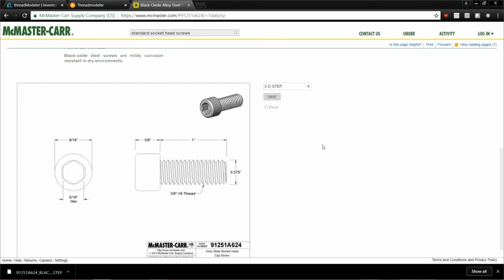If you can't find something in the existing Content Center library, well, we all know Inventor's got its own Content Center library with a lot of these fasteners in it as well. If some of those don't meet your specifications for some reason, or you actually want to download the actual purchased part, just because it's got a CAD file associated with it, go ahead and add some of these commonly used ones to your custom Content Center libraries, and that'll be really useful.